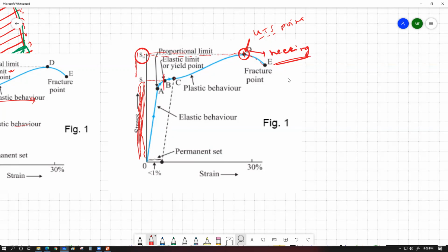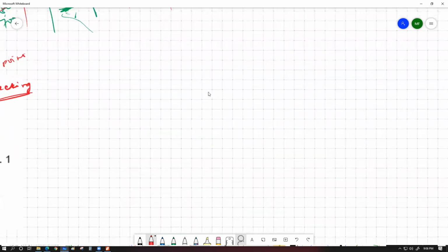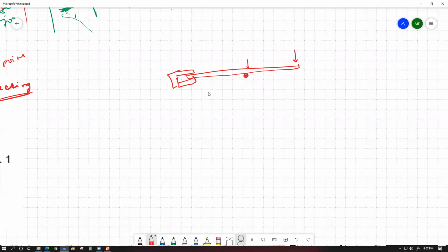মনে করো আমি একটা জিনিস তোমাদেরকে বুঝাই। Let's say this is a metallic rod. Okay, we want to bend this rod at this location. How do we do that? We clamp this part over here. This is a strong clamp. We provided a pivot support over here, strong support. Then we apply some load over here that can move around. So if we apply this load in a circular pattern like this, we can make this rod bend in a shape like that. ঠিক না?